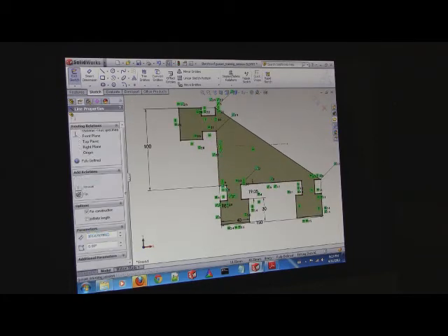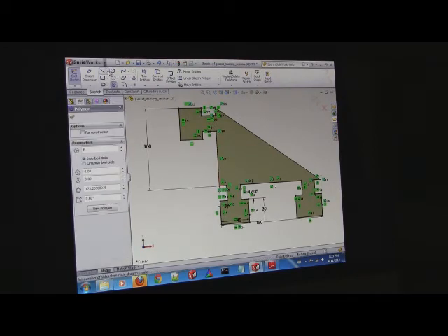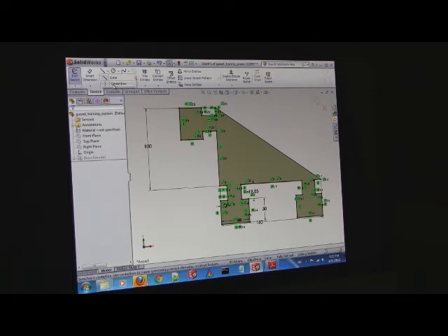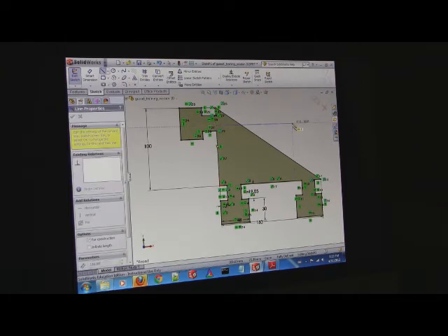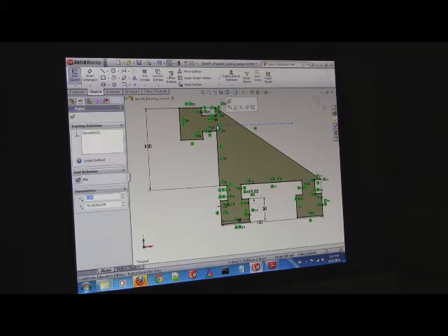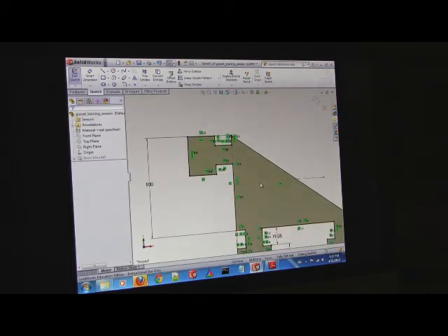Okay, so does everyone start from here. Take a construction line. Construction line is the same as the center line. Press one in here on the top corner and one down here on the bottom corner. Press escape. Now take another center line and put it somewhere around here. Everybody got those two lines? Then you press this point here, hit Control, and select this line here. Everyone see on my screen down here it says midpoint? Press midpoint. So now we have a line in the center.